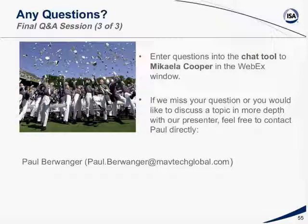If the operator response interval between a high and a high-high is 1 minute, then you don't really need another alarm because it's going to be too fast for them to respond. And once again, going back, if the high alarm is already configured at your highest priority, then you don't need another alarm as well. It's only if there's time for an operator to respond in that interval between the high and what you're calling the trip point. If you can get another meaningful alarm in there from an operator time to respond perspective, then it makes sense to configure it. If not, and it all comes down to operator time to respond, if they don't have enough time to respond to the next alarm, it should not be configured.